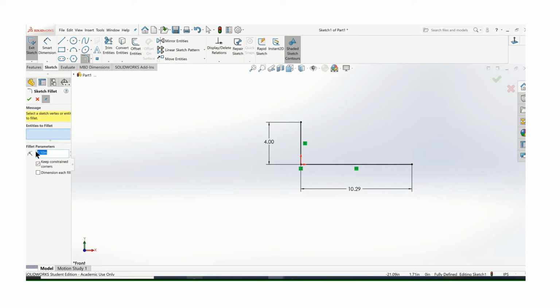The smallest radius that you can bend is 3 inches. Now I'm using a small diameter, 3/4 tubing, so I can use a 3-inch radius, but the smallest I want you to use for 1-inch tubing is a 3.5-inch radius. And whenever you bend tubing, you have to leave enough room. This run here is 4 inches long, so I can get a 3-inch bend in there. If you put it exactly at 3 inches, I don't think it'll bend. You have to have it beyond 3 inches to put a bend in it. So that'll be my path.